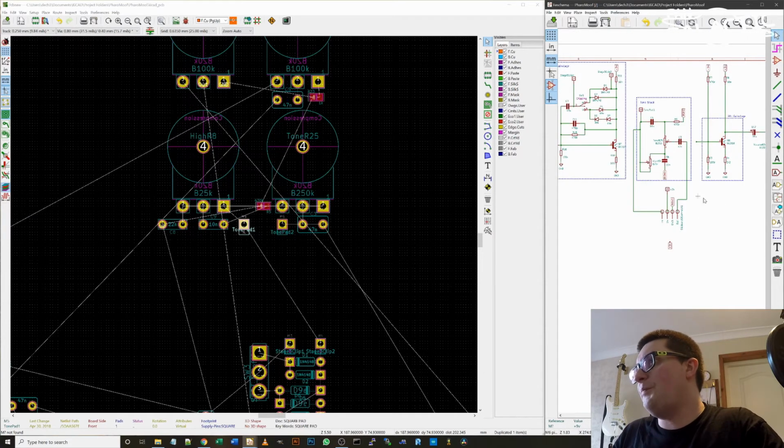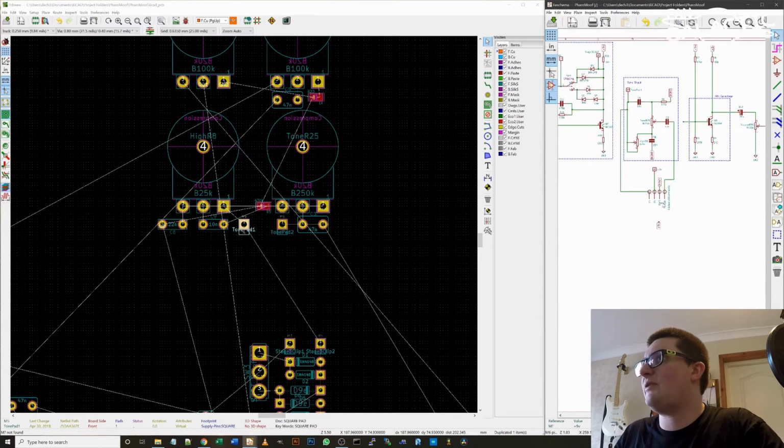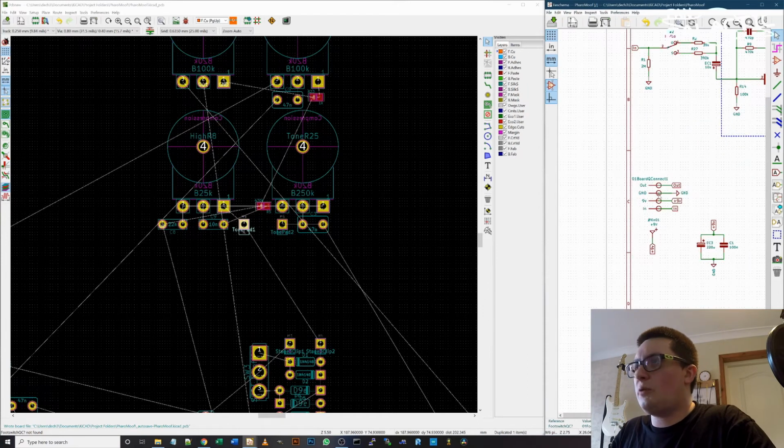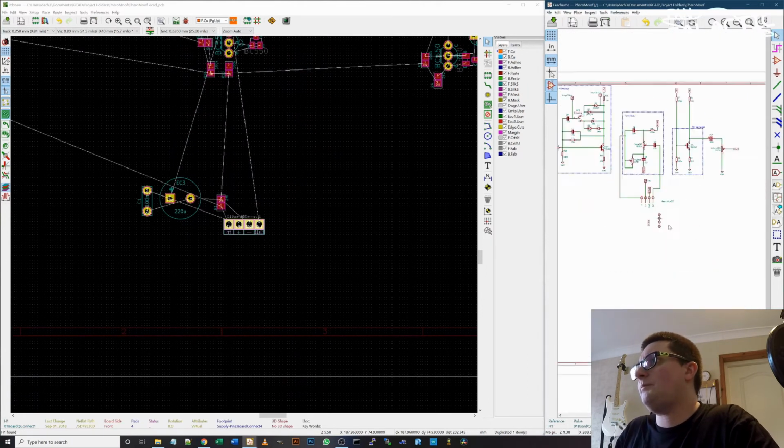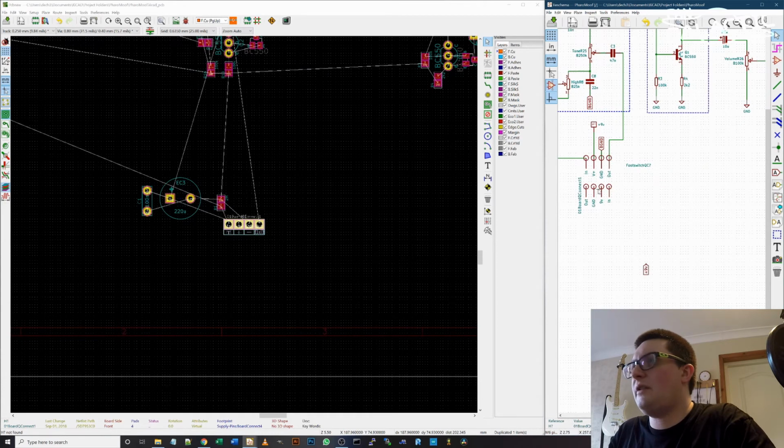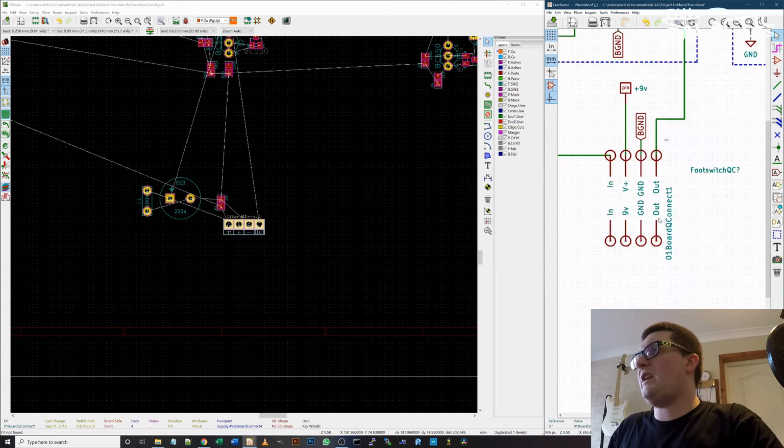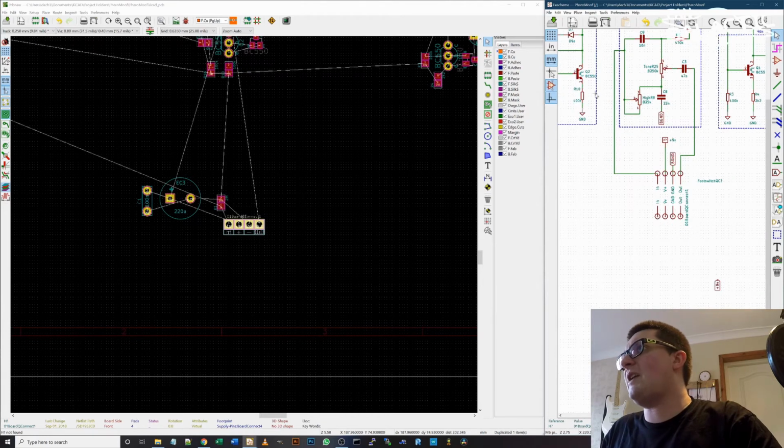But we're not going to connect that label to it, because if we want to be able to cut this bit of the board out separately, we don't want any traces actually joined to it. We're going to have to put in another header attached to these bits of the circuit that will join to it. So I'm going to create another one of these board quick connects by copying. I could put this anywhere, but just to make it obvious, we'll follow the labels here. Although this is going to be an out from this circuit, and this is the into this circuit, I'll follow these labels.